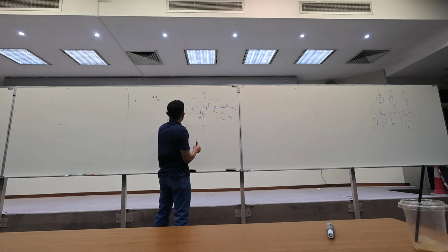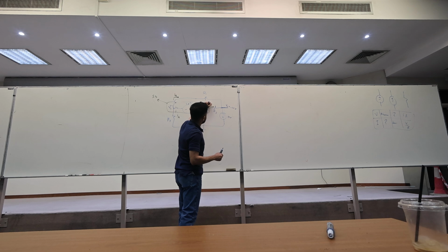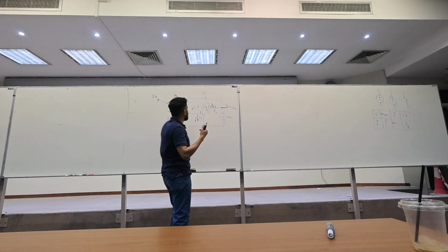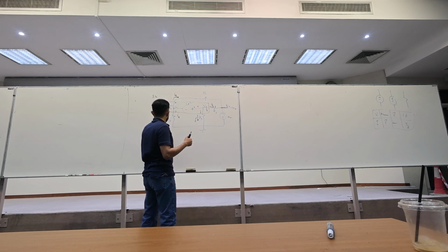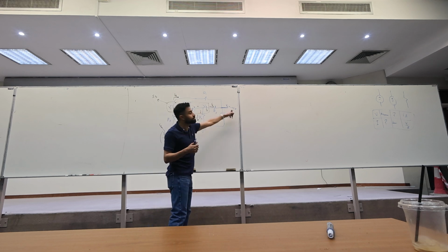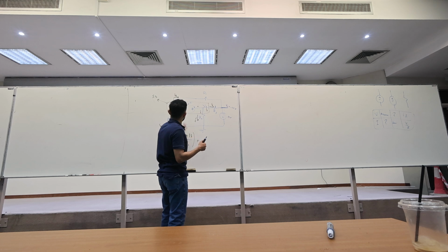So we call them IA, IB, IC, ID, and you need to add a constraint equation later. So how many unknowns? V1 and V2. So let's write the equation. V1 minus 0 over R2, this is IA, plus V1 minus 15, it is V1 plus 15 over R1. So we finished IA and IB.